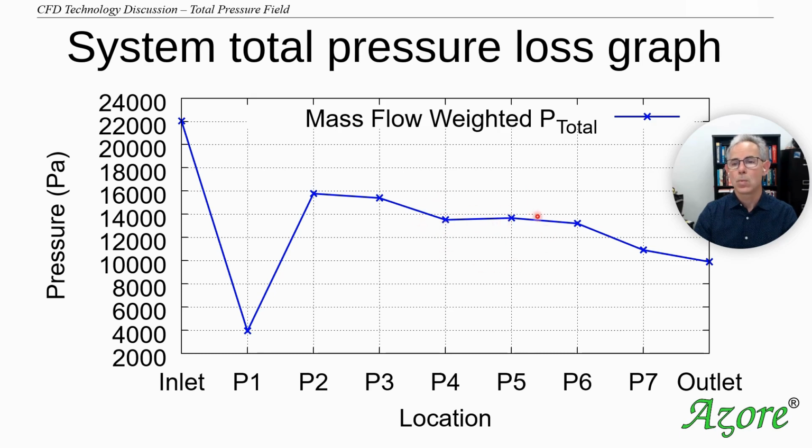And this is where you could really have problems if you're looking at 3D flow structures that are very complex. You can be in the situation where you're trying to evaluate the pressure loss between 2 points, and you might see something like this if you use mass flow weighted averages. It would be confusing, and then you're trying to decide, is that an error, is my model not converged? It makes it a little grayer as to what you're looking at. So that's our mass flow weighted average.